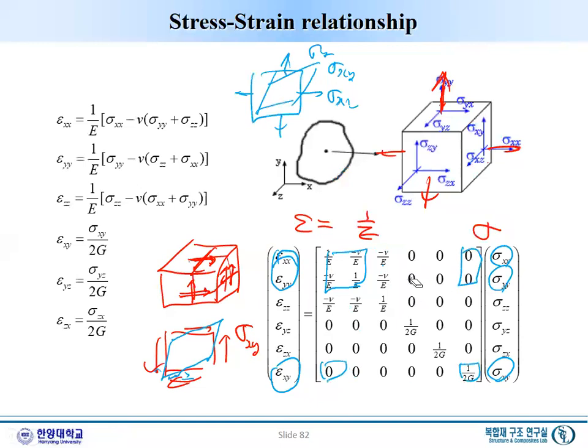And so this matrix, since it's 3D, we can shrink to 2D, shrink to 1D. What is a 1D? This, and that, right? That is a 1D version. So again, this is the material property. We start from a very strict F equals Kx. Now extend it to a concept, sigma equals E epsilon. And then we reverse: epsilon equals sigma divided by E, and the 2D version and 3D version.